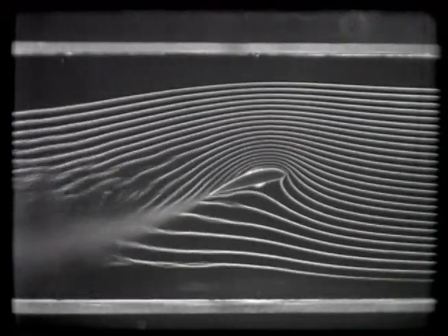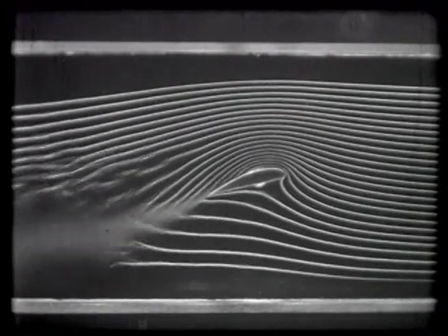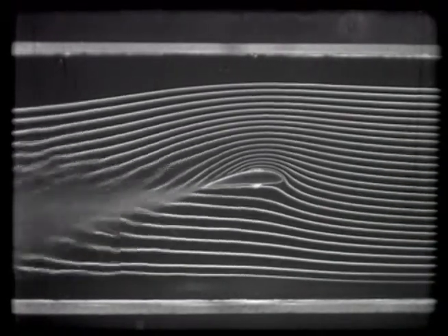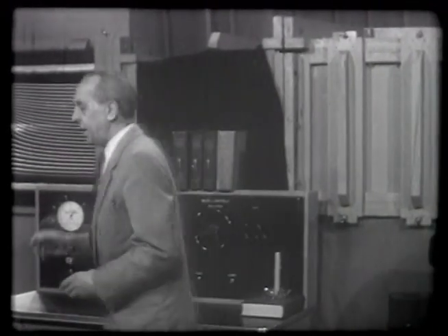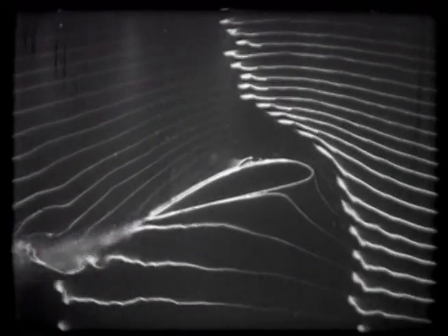But you see that at once we have a very large lift. Now you can see this even better if you look at a slow motion film with pulsating smoke, which we have here. And there you see at once how fast the flow moves over the upper surface. And as you remember, the difference between the smoke lines on the upper surface and the lower surface is a measure for the circulation. And you see here how much circulation we have with this blowing slot.